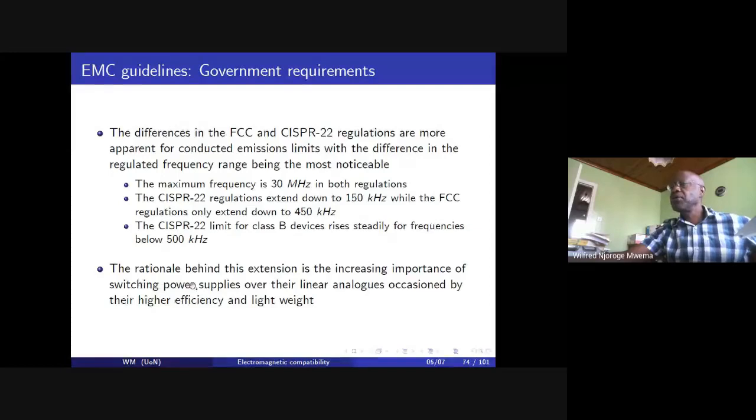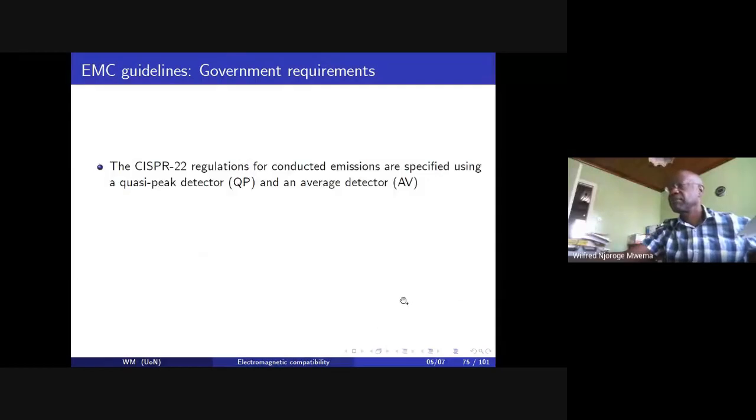Then we use a chopper, that is a switching circuit, to chop that rough DC into high frequency pulses, sometimes up to 200 kilohertz, and then use a pulse transformer, which will be much smaller, and therefore you don't need a magnetic core. You can use even an air core to drop them down to a lower value, and then you use rectification again and smoothing, with a smaller capacitor to smooth that to get the DC.